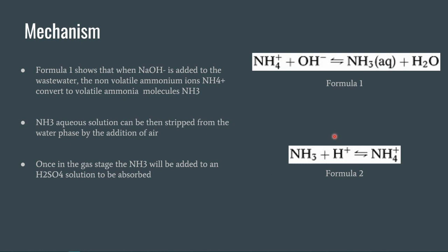Now, some things that needed to be considered before an experiment was conducted were the initial pH of acetylene purification wastewater, APW, the airflow rate, APW temperature, and stripping time. These variables would affect recovery percentages and effectiveness.